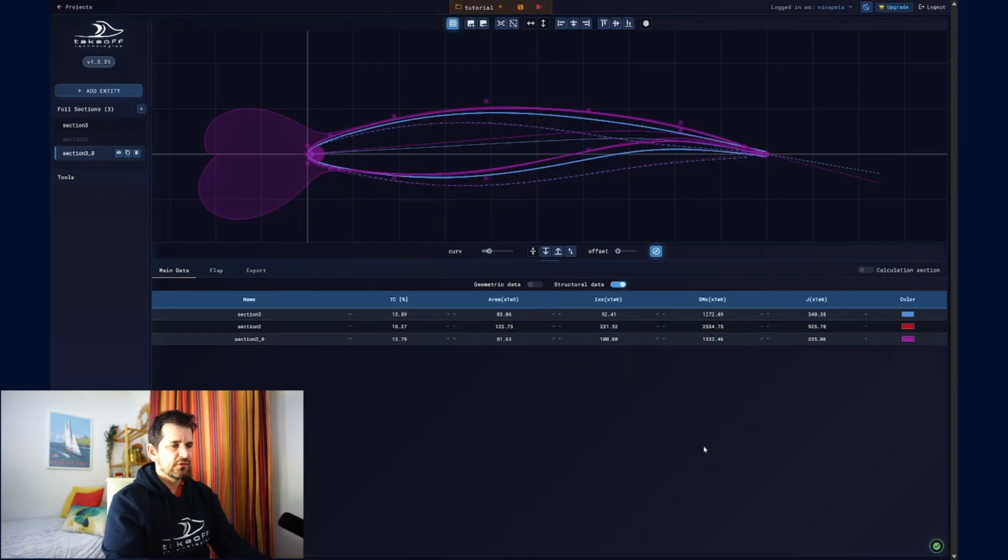The section modulus is the parameter to understand the stress you will have on your section. So the more section modulus you have, the less stress you will have for the same bending moment. Again, normally all these structural parameters go up and down. Obviously, if the inertia grows, all the rest of the parameters grow.